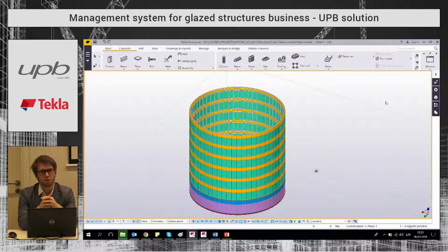A sales model needs to be about level of detail 200, just simple geometry so that you can get amounts. And why we need a 3D model: the sales model is done in 2D, and engineers afterwards have a hard time comparing the sold project with what they have projected.